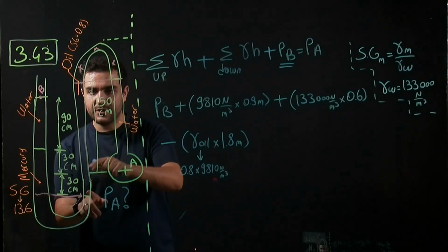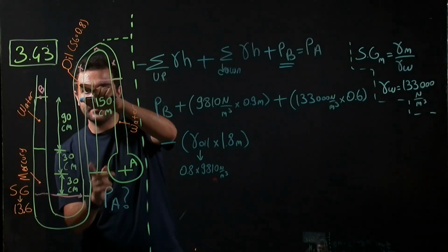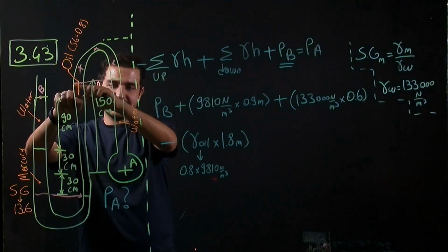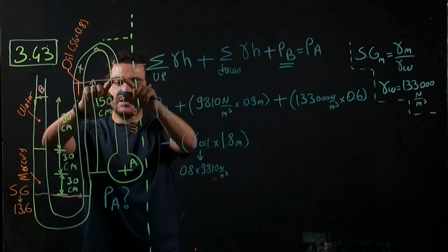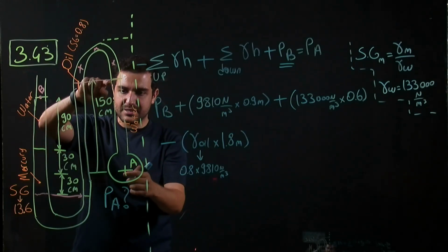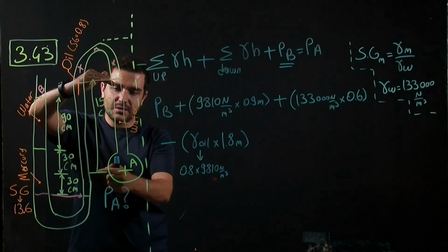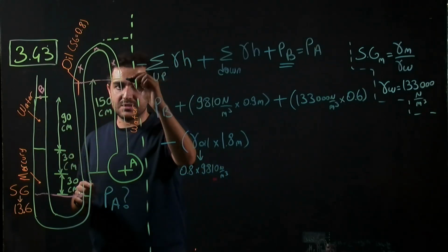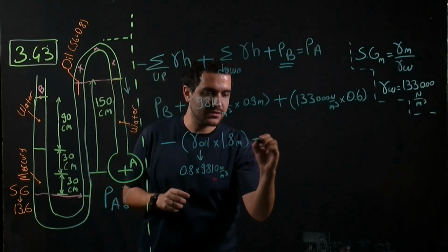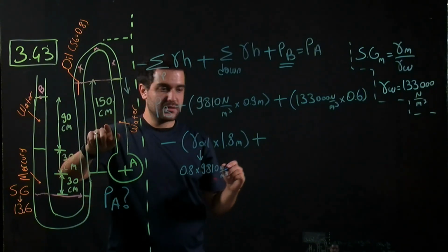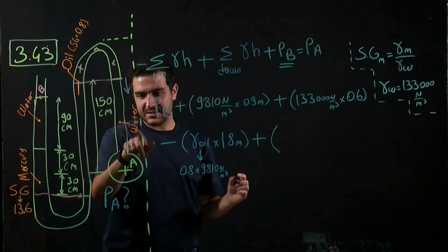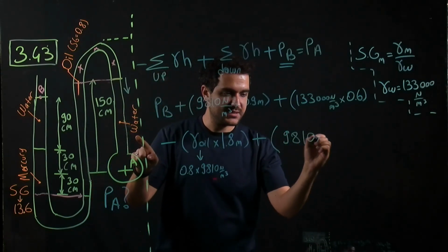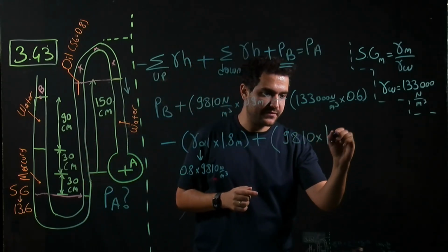So we calculated the pressures in this section, and as I mentioned, we have the same pressure here until here because they are at the same horizontal level. And after that point, the only remaining part is from this line to this line, which is 1.5 meter section. And again, you should pay attention that we are actually going down here, so it will be positive again. And it states that it is water, so we have specific weight of water times 1.5.